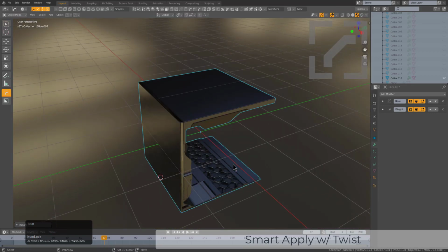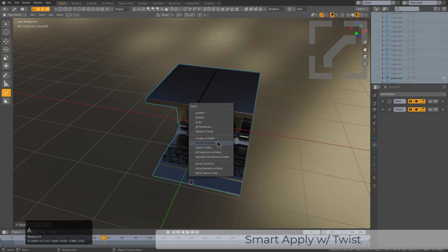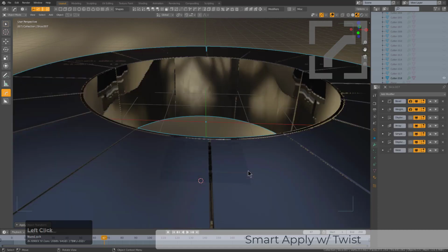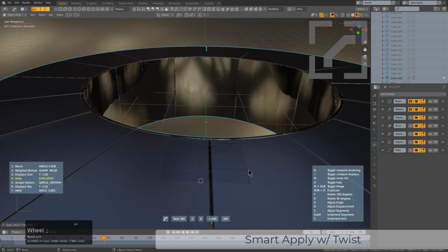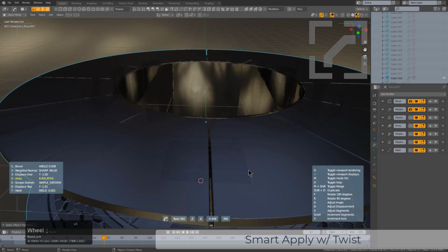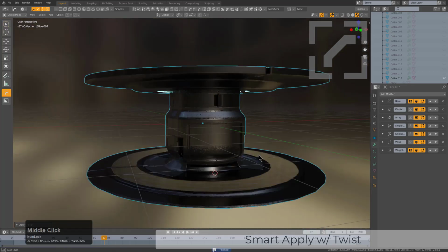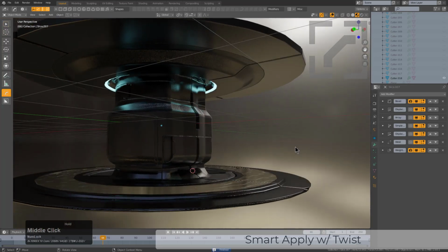So now the next thing is to just rotate this so it's frontal on the x-axis, and we can just take this and use something like twist 360, which will get us a much more interesting result. Since I'm running this all in render mode, and this is a pretty heavy mesh with bevel still live on it, it's going to get a little bit slow, but we'll just dial that back in real quick. But we see that I'm able to turn this into a very interesting twist of a different design.